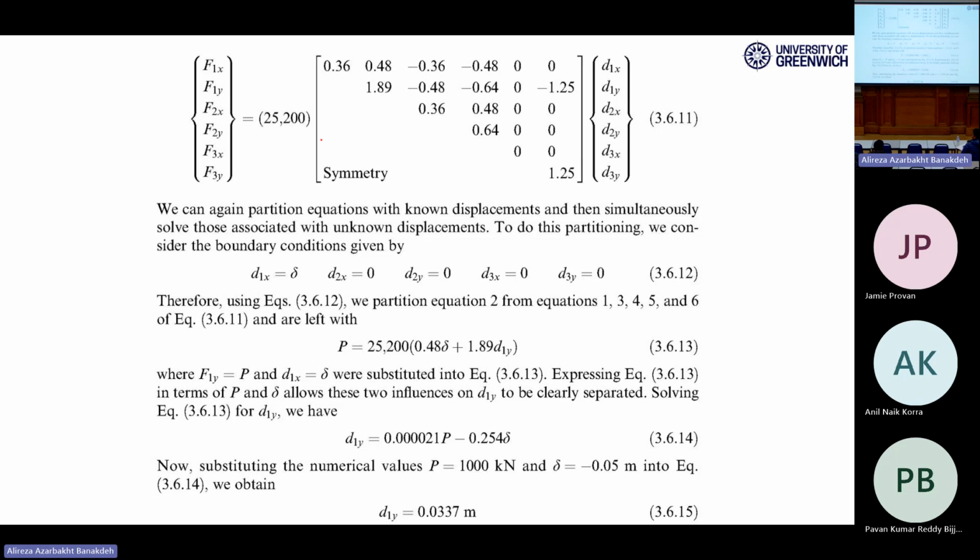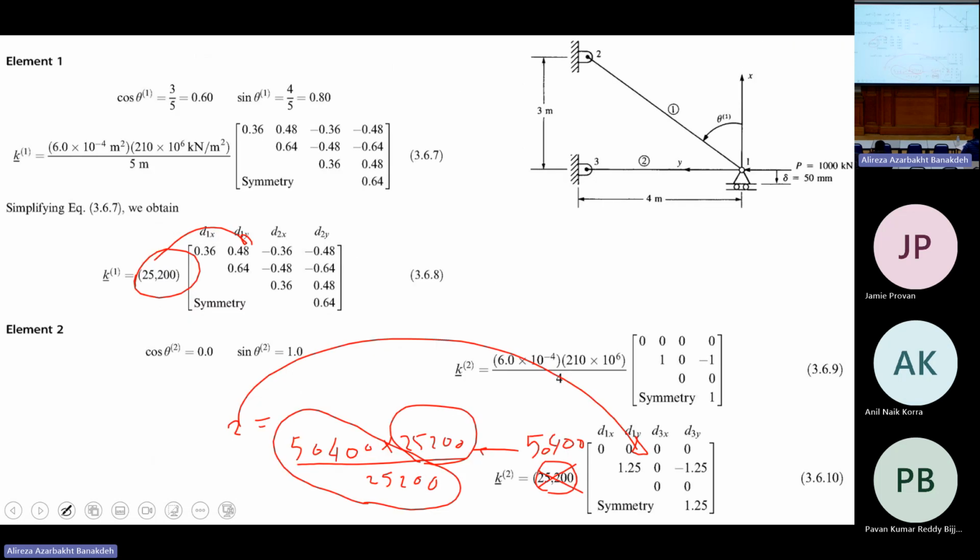Anyway, when we assemble the total matrix for the whole structure, we know that this matrix correlates the vector of deformations to the vector of forces. For the vector of deformations, if you take a look at the structure, you can see 5 of the degrees of freedom are restrained, and only 1 is open to move.